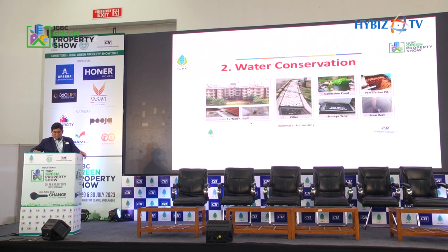And there's another method called the percolation pit or borewells. This concept is for groundwater recharge. So what happens is the surface runoff rainwater would be led into these chambers and pits, and this will enable the ground to absorb the excess rainwater that is being generated.